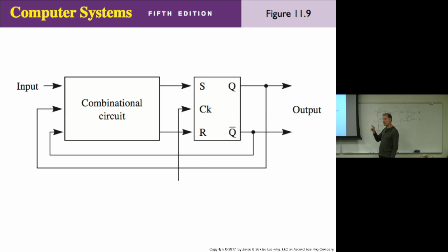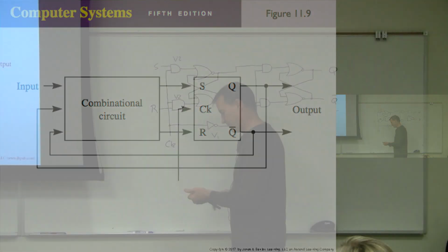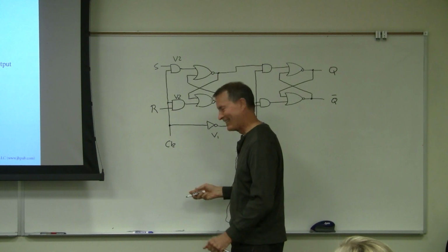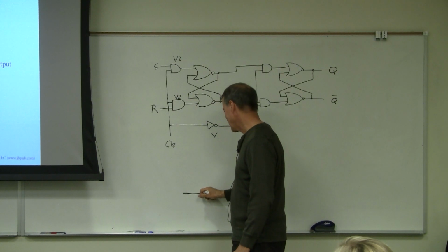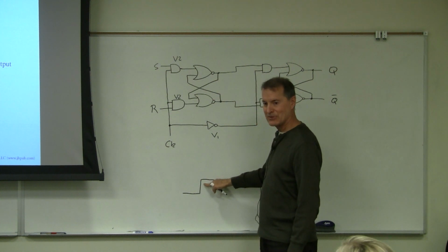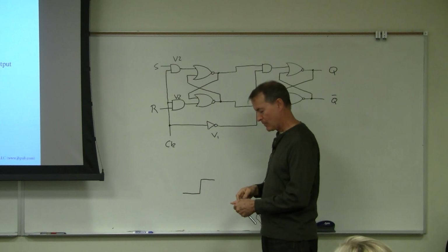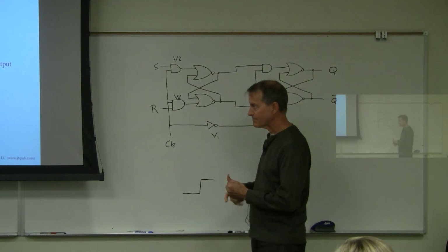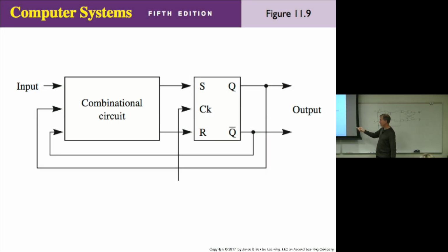Now imagine this scenario. Now the clock strikes 1. Hickory dickory dock. Now the clock goes up to 1. Now when it goes up to 1, what happens? Q becomes 1, and then Q bar becomes 0, because S is 1 and R is 1, right?